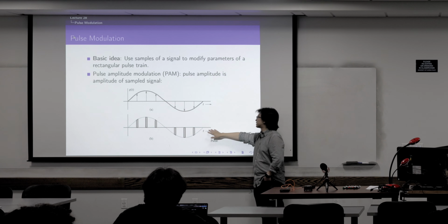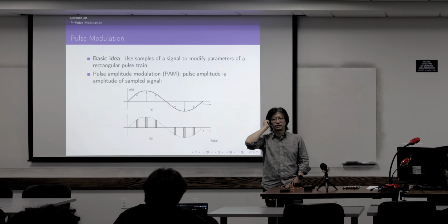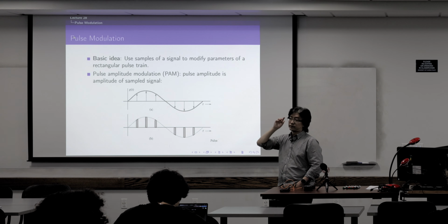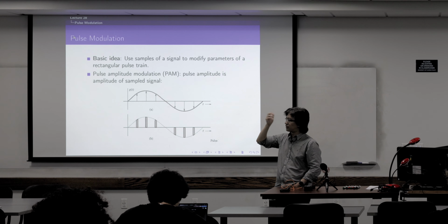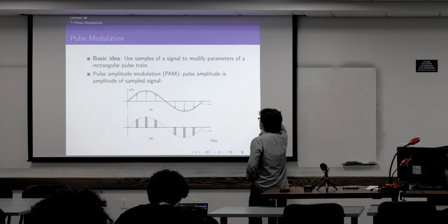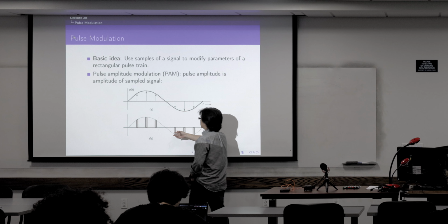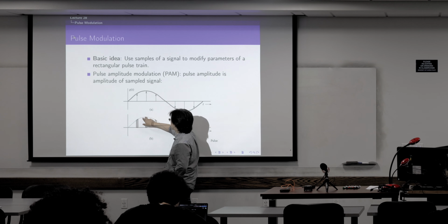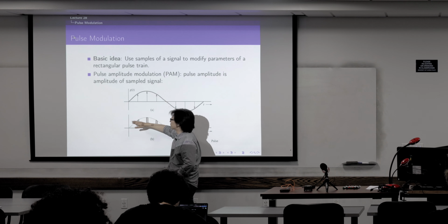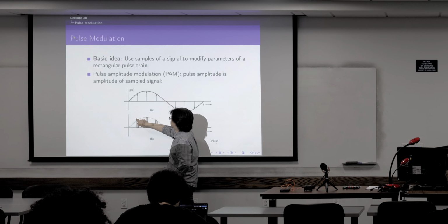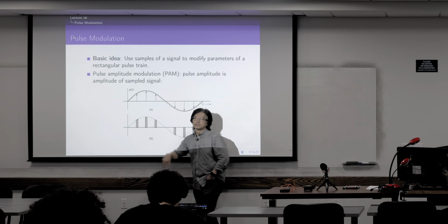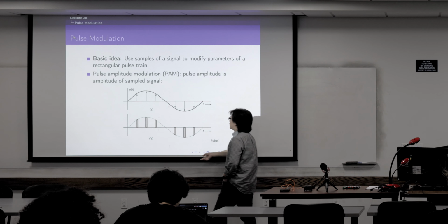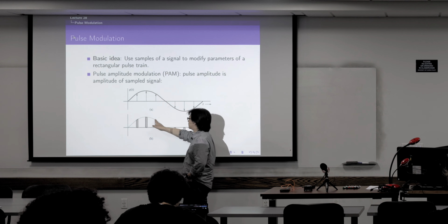It's called pulse amplitude modulation. You can find this is very similar to amplitude modulation in analog communication. Now what we're going to transmit is all these pulses, but the difference here is that all of them will be quantized. They're going to be at fixed levels, so this value will not be all the real numbers. Now the question is how to transmit the value here.